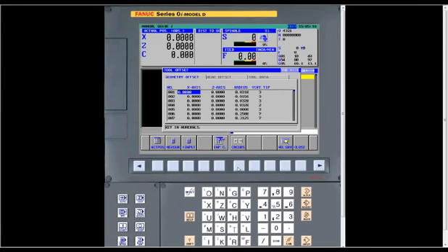All right. Question here. When you touch off the tools, normally do you have to input them again, or will the iGuide pull them into the setup? Oh, yes, yes. Because this is the same data that's on the CNC side. It shares that information when you measure a tool. It will pick up the data from your standard tool offset screen.